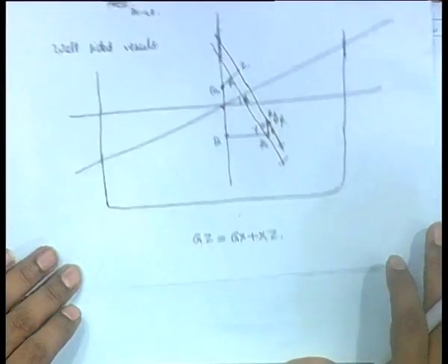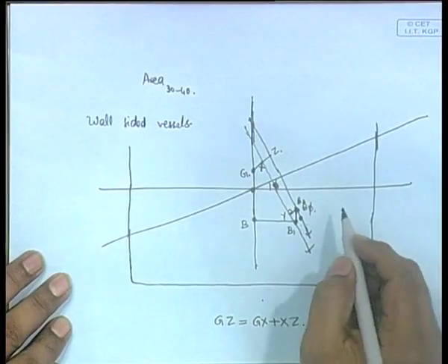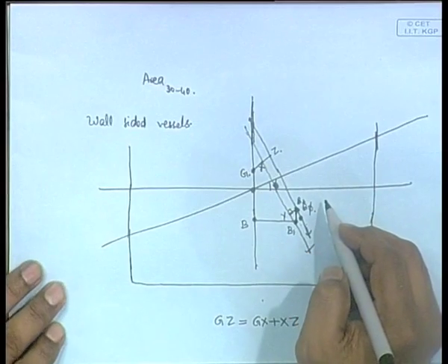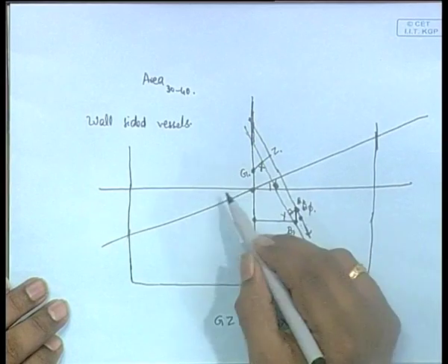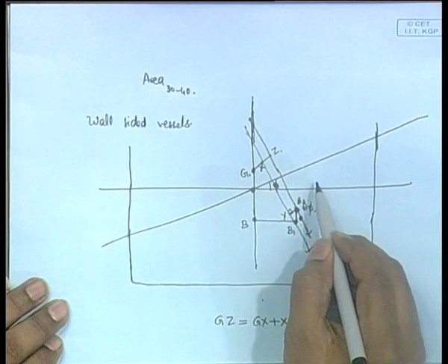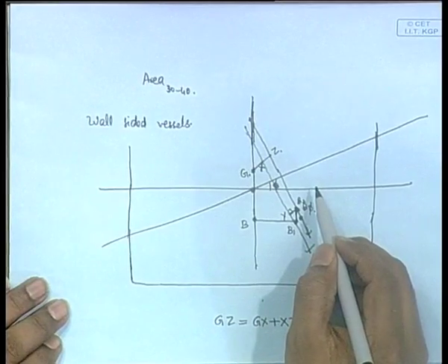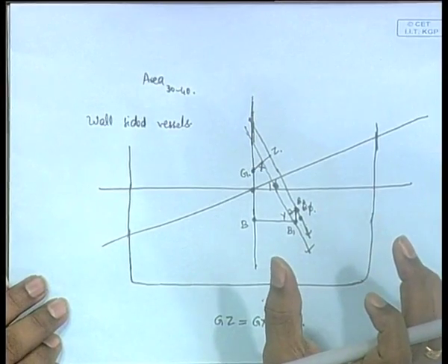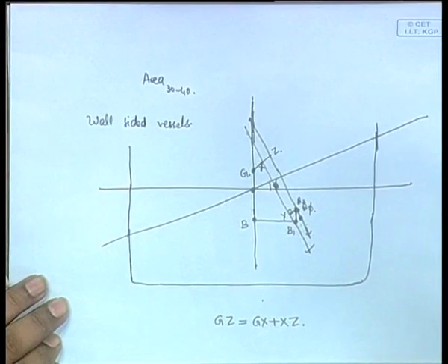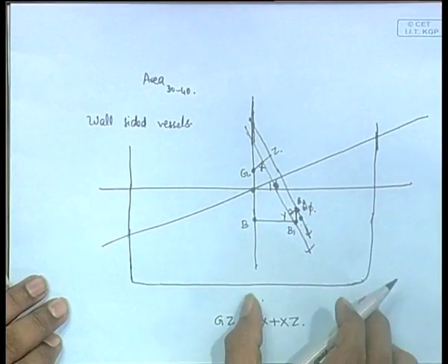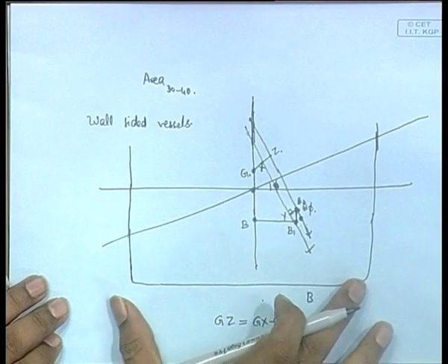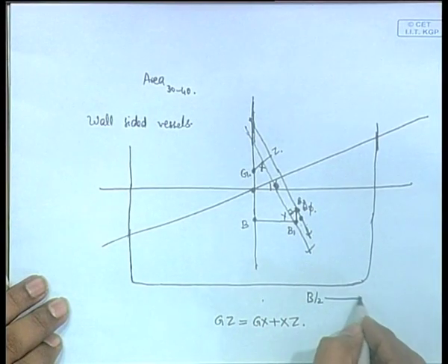Now we are doing a similar thing; we have done a couple of these many times, so I will not repeat that. There is a shift of a wedge from one side to another, the movement of one volume to the other side, and we have also talked about the coordinates of the center of that volume, which we can call the center of buoyancy or the center of gravity of that volume. If the whole distance is b, then this is b by 2.